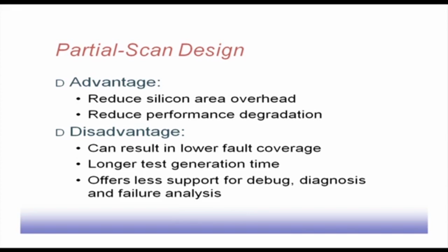It also offers less support for debug, diagnosis and failure analysis, because of the same reason: the entire circuit is not visible. Many of the flip flops continue to be normal flip flops, so they are not visible at the output.